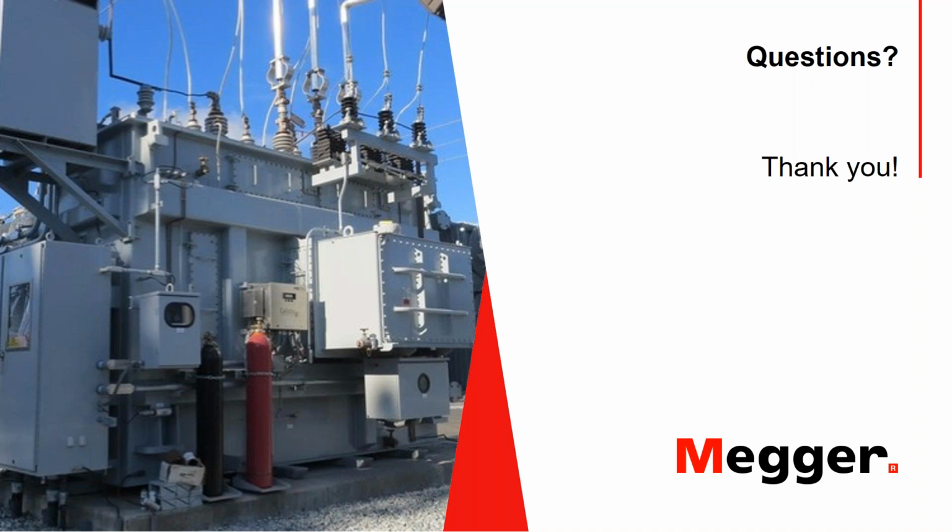Thanks, Samir. Dinesh, when should the dual winding injection be used? So Samir covered a couple of case studies where he talked about dual injection. Basically, the idea is for us to saturate the core faster by having more ampere turns, which would result in more flux. More flux would result in faster core saturation.